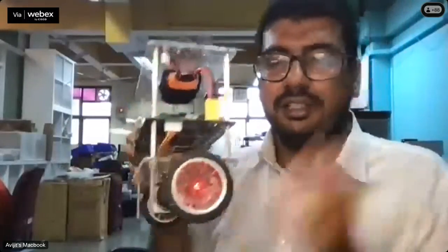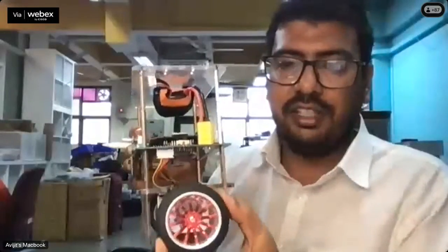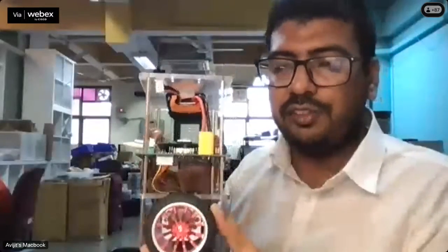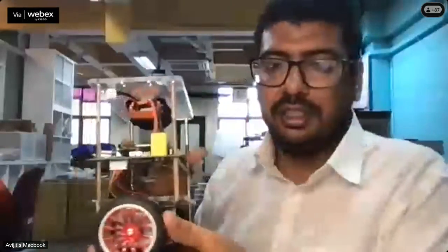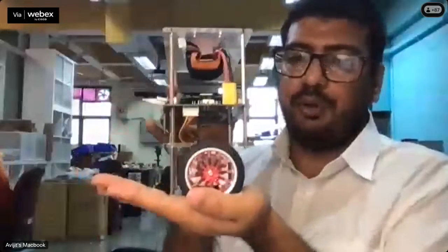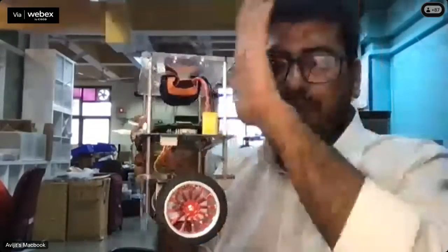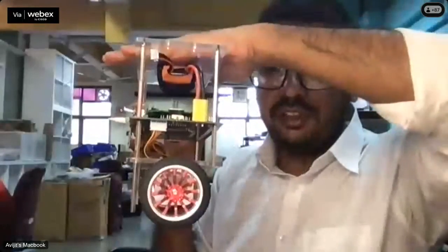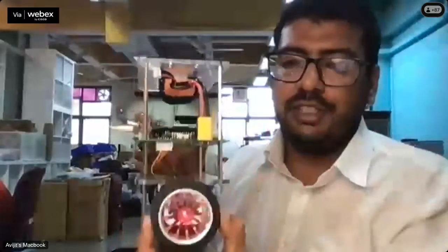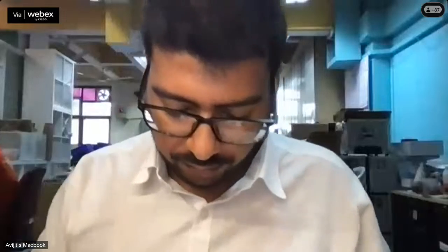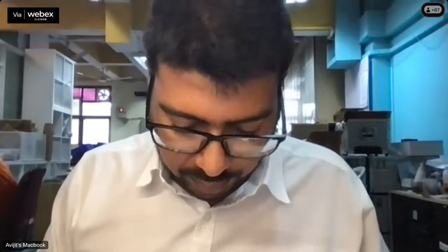After that, third, we have theta dot of wheel. If theta dot of wheel is very loose, that means the robot will move forward and backward a lot. So we want to keep the bot stable at one point and balanced. So we want to put restriction on the angle of the body, the rate of change of the angle of the body, and the rate of change of the angle of the wheel. And the angle of the wheel is least favorite to us. So by that logic, coming back to the drawing board again.